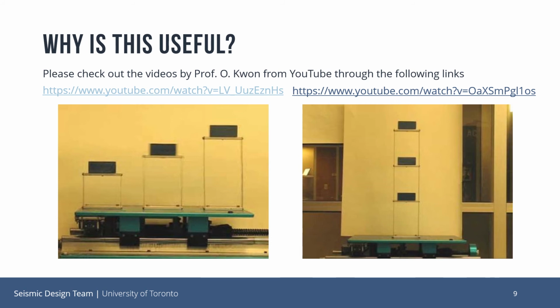So you can see here 3 different towers, basically. The only difference being their period. They all have the same math, just they're different lengths, and the taller it is, the more flexible it is. What's going to happen is this shake table, which interestingly enough is the same shake table we have at U of T, I'm pretty sure, is going to slowly increase how fast it's going back and forth. And you're going to see it hit each one of these different models' fundamental frequency, and it's going to go into resonance.